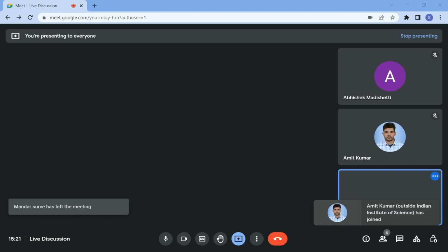I mark it here. And similarly, the construction says that since you already constructed this at 45, you already have a locus of point B in the horizontal plane. So this is the locus of all points B which are at 45, which is a constant line, and the locus of point B which is at 30 degrees with respect to the horizontal plane is a circle in the vertical plane.